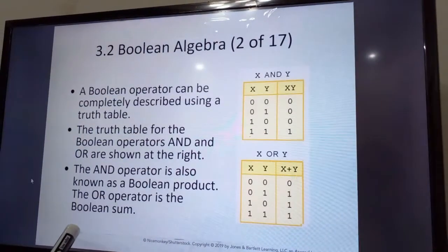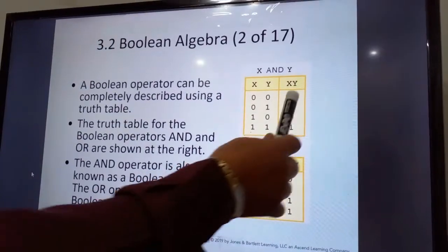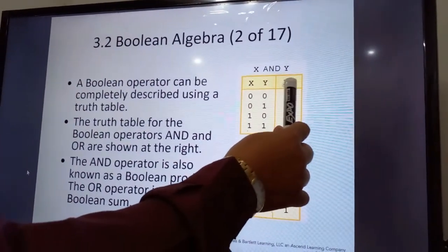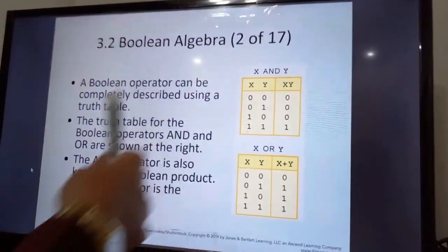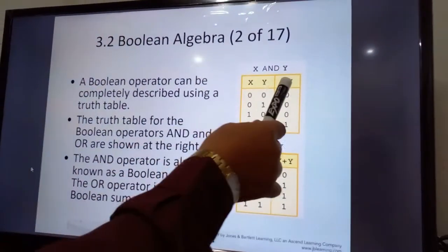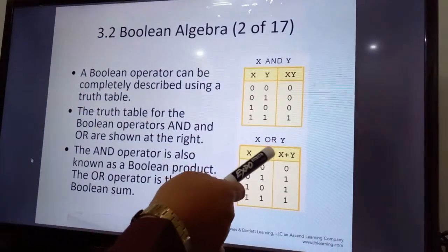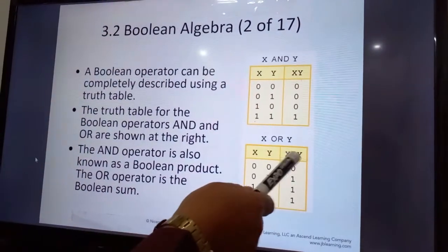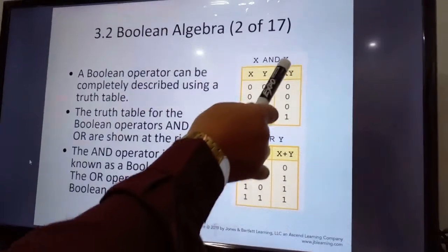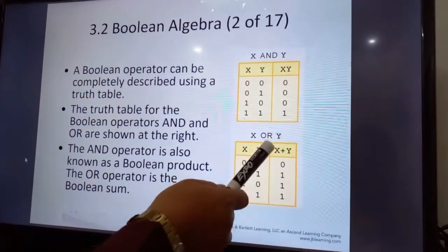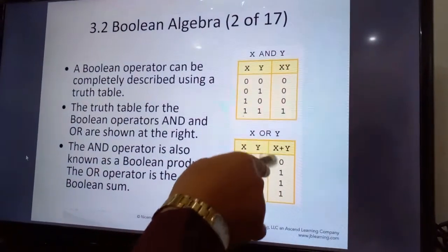So in your AND, the function of AND is multiplication, meaning product. Multiplication is the operation you use when you create a Boolean equation. In the truth table or Boolean algebra, OR is addition, which is plus. So in your equation, we have x and y, meaning you use multiplication. X plus y, so addition is what you use for OR in Boolean algebra.